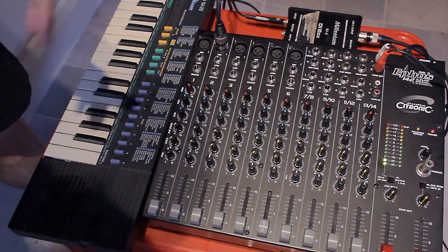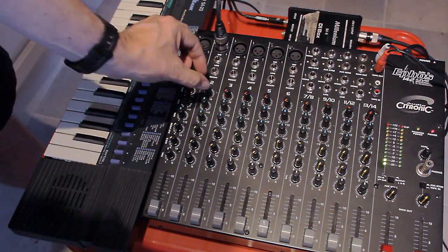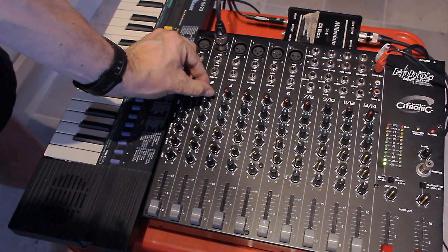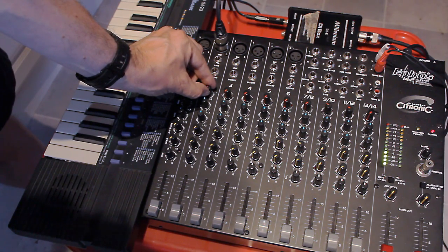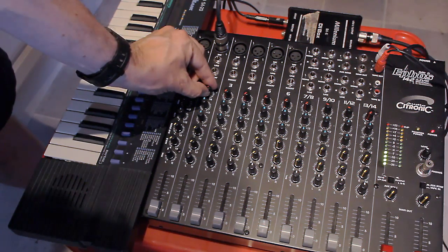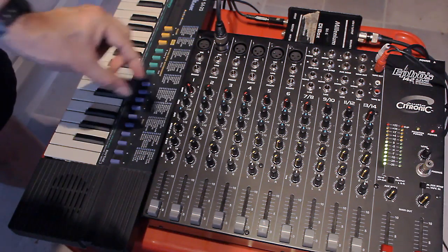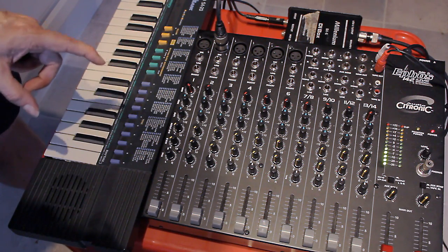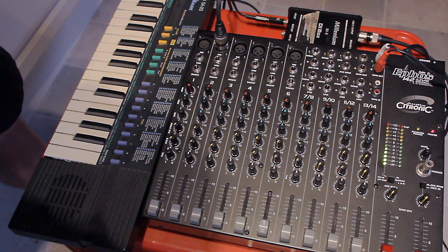Keyboards and guitars often produce a higher level signal than a microphone. But okay, we can now gradually tweak the gain up, watching the level meter until we're just lighting all of the greens. There we are, that should just about do it. About there, might get the odd flicker from the yellow. Now we have correctly set the gain for that channel. A little bit more, there we go. That's now correctly set.